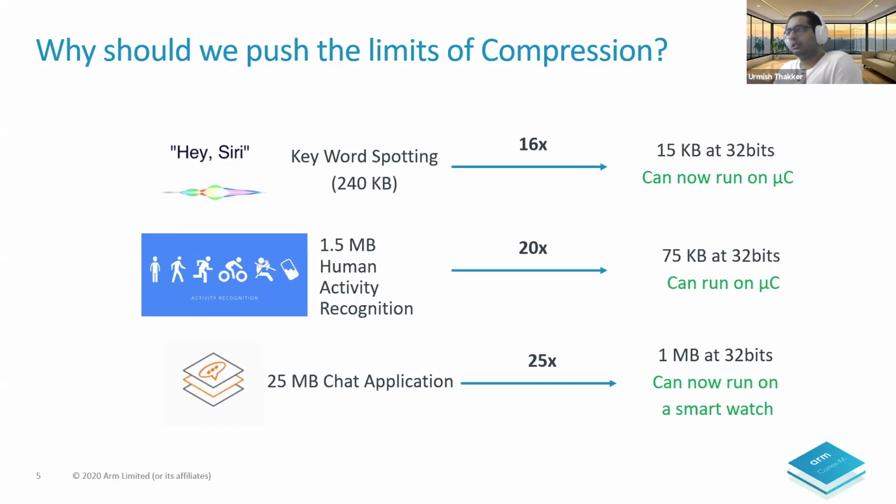The chat application is impossible to run on a Cortex-M device right now with the 25 MB of space that it requires. But after 25x compression and probably an 8-bit quantization, you're looking at around 250 kilobytes. And again, you enable this application to run on a Cortex-M device.